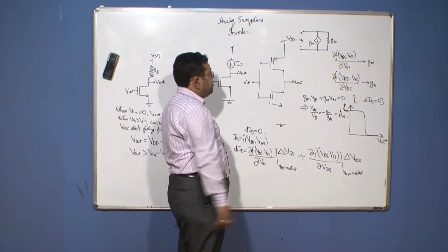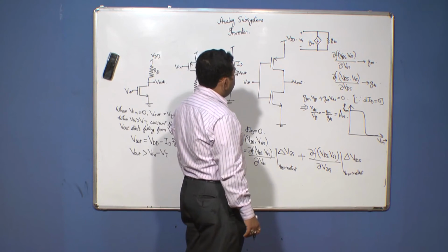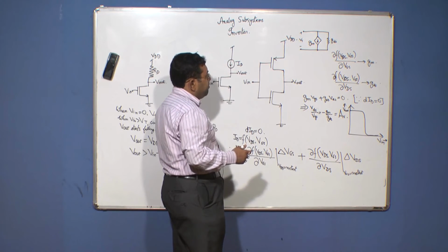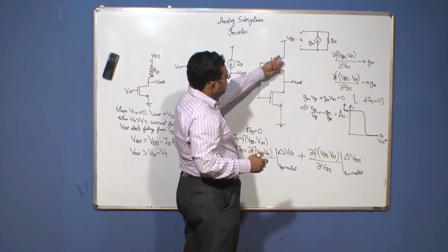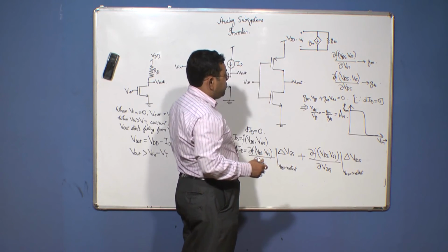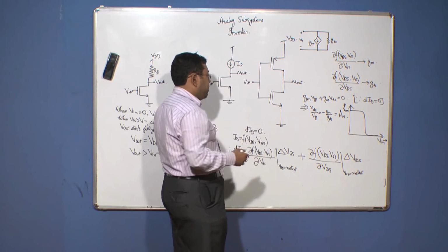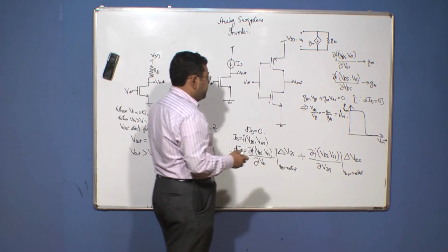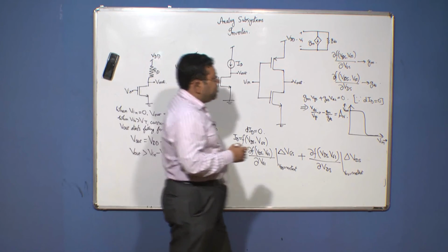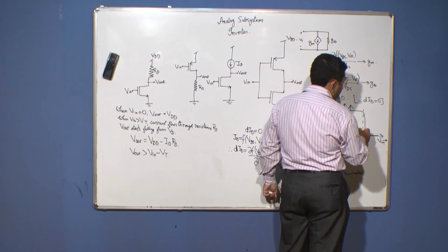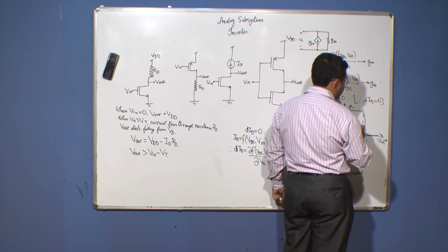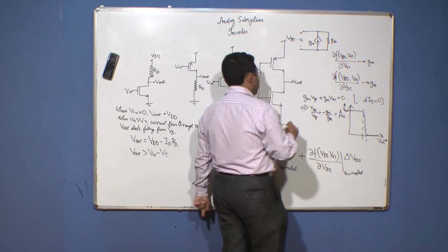In this CMOS push-pull inverter, the current basically flows through the cascade connection of the NMOS and PMOS transistors and down to the ground. Now over here we can see a sharp change in the output with respect to the input, which means the gain is very high in this region.